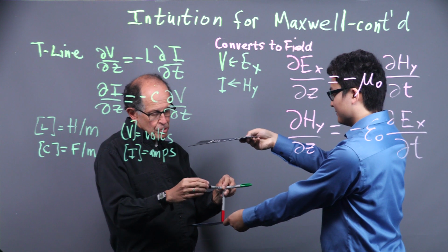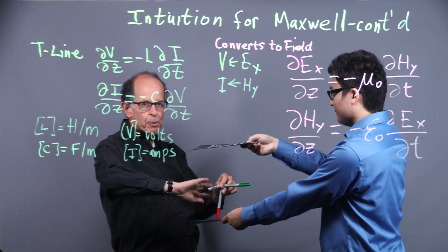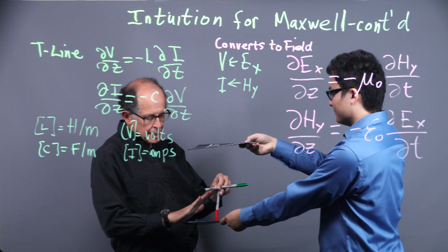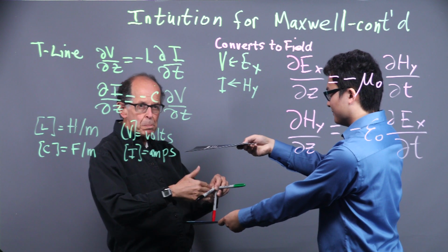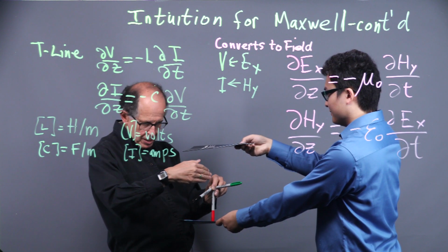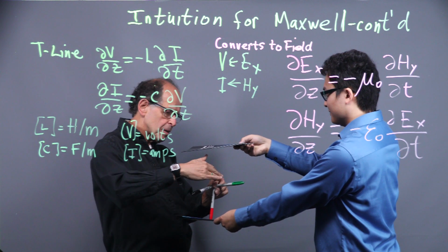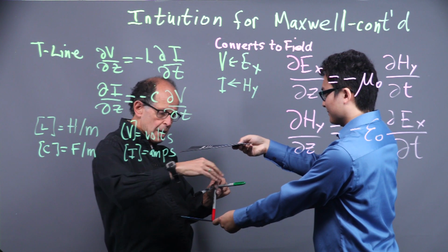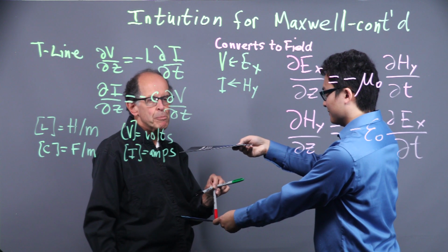Now, what happens is the vibrations are basically restricted at any point to the plane containing the magnetic and electric fields. So this plane is perpendicular to the direction of energy flow, along the direction the wave is traveling. And for that reason, it's called TEM propagation.